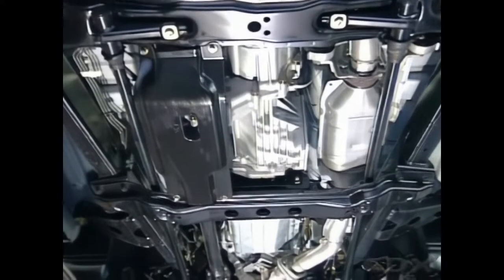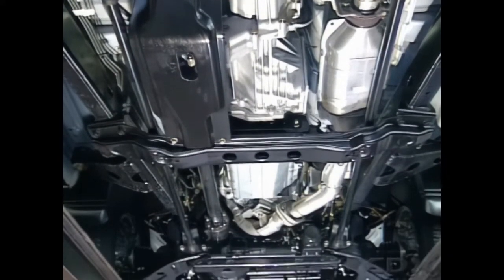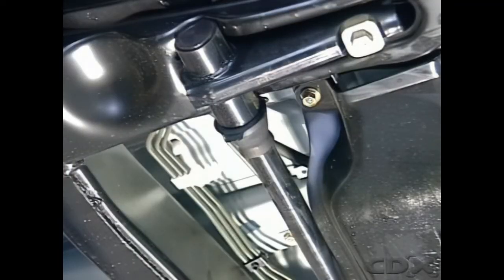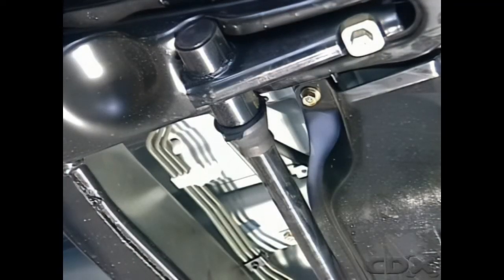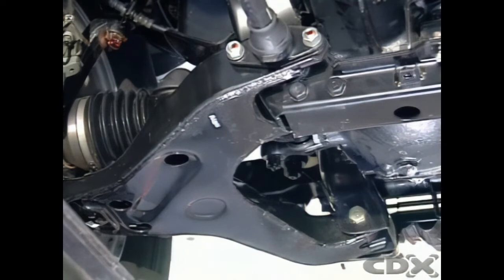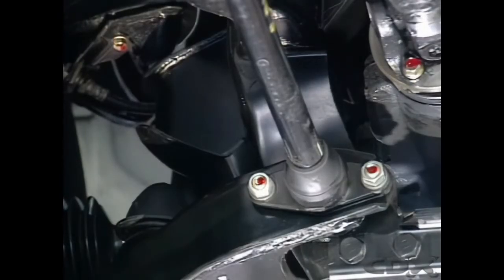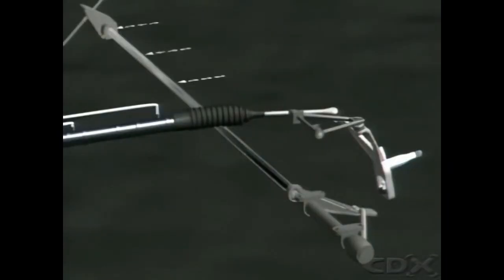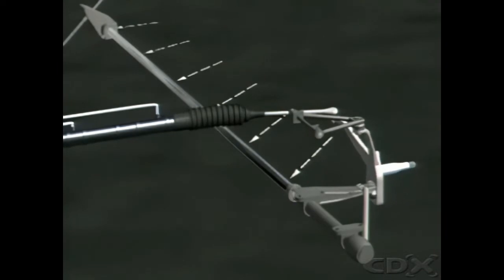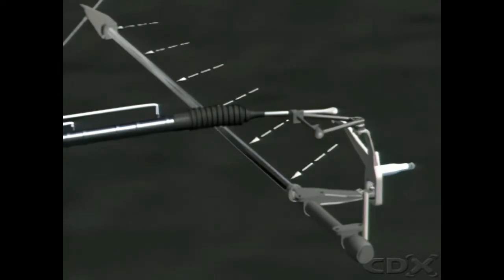A torsion bar is a long alloy steel bar fixed rigidly to the chassis or subframe at one end and to the suspension control arm at the other. The bar is fitted to the control arm in the unloaded condition, and as the control arm is raised, the bar twists around its centre, which places it under a torsional load.